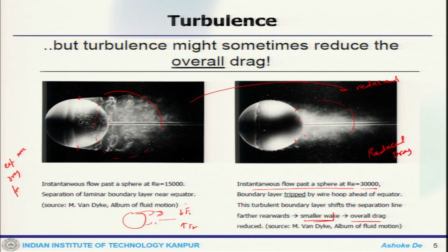But if you leave those factors aside for the time being, and just think about one side smooth and one side rough, as the ball approaches the batsman, that is where the swing happens because of this asymmetry in the radial forces. The primary reason behind that is the fluid mechanics. In one case it is a laminar separation, in the other case it is a turbulent separation. So in this case the drag is reduced, or the adverse pressure gradient zone is low, and in this case it is high.